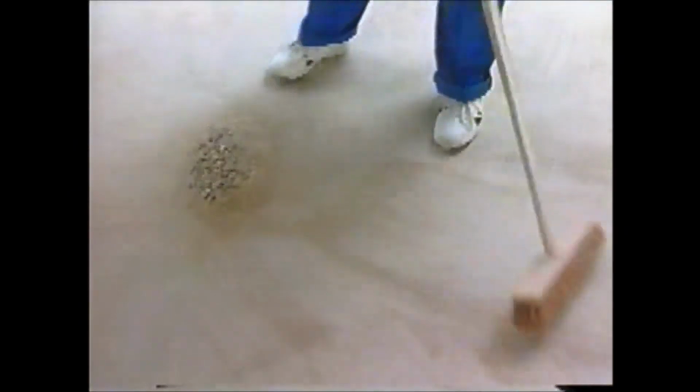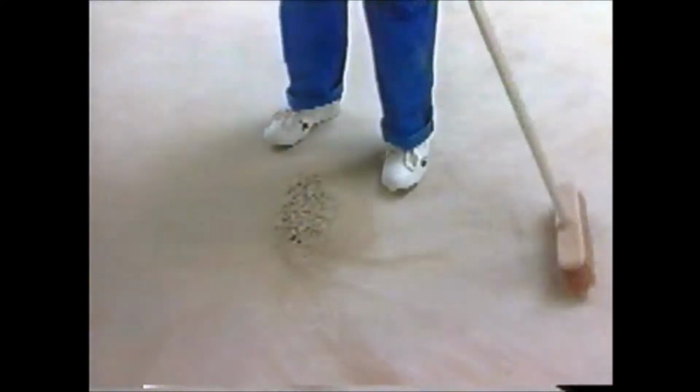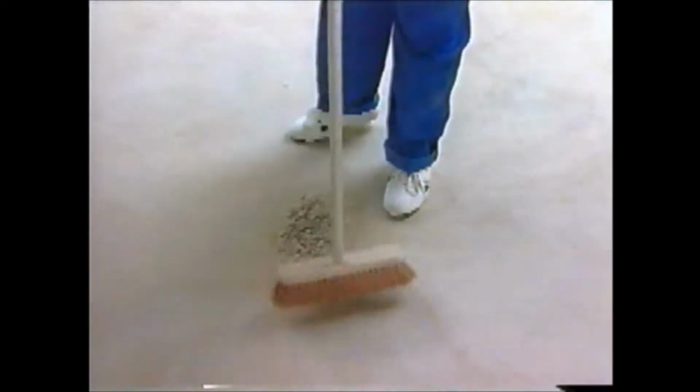Before the installer can perform any work, an examination of the subfloor is required. This makes it possible to define the preparation work required before installation of the floor covering in conformance with the technical specifications, the various technical recommendations, and manufacturer data sheets for the products concerned, as well as the various related standardized technical documents. Is the slab new or old? Is the surface rough or finished? Is the concrete plain or topped? Have the plumbing and painting work been completed?